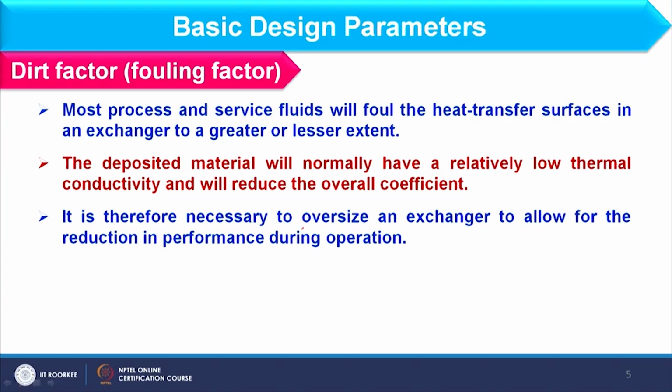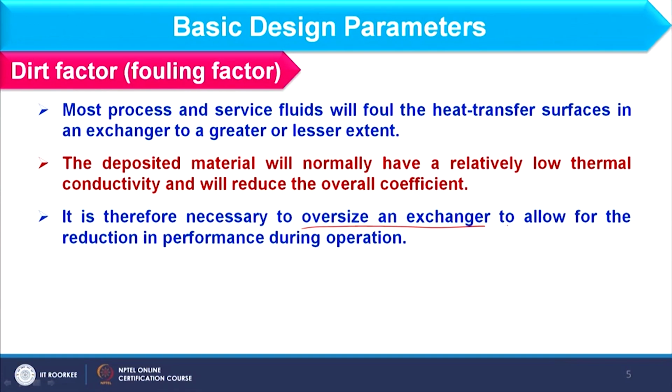So, if I am doing so, what I am doing basically is oversizing the heat exchanger. I am oversizing it because I am already considering a lesser heat transfer coefficient, and this oversizing will compensate for the reduction in performance during operation.